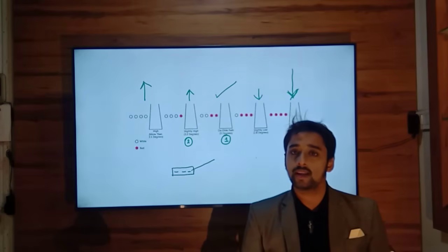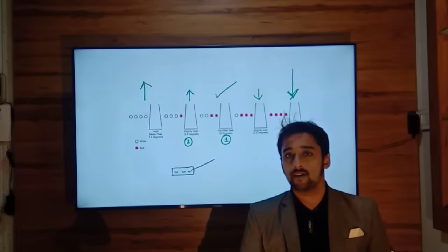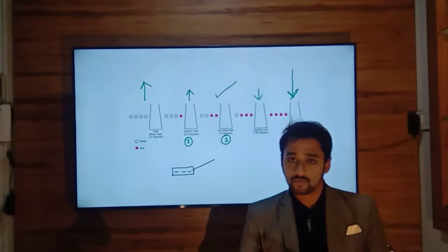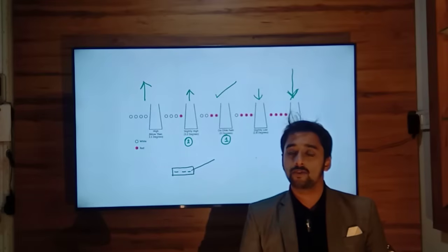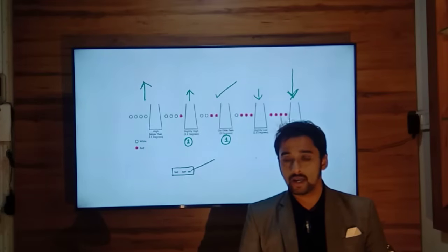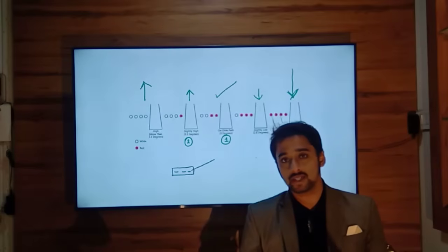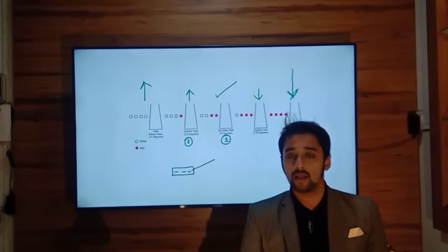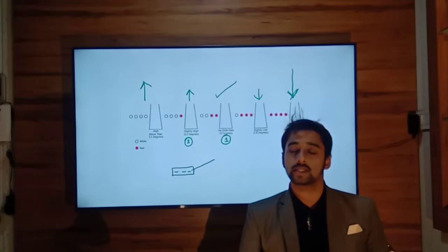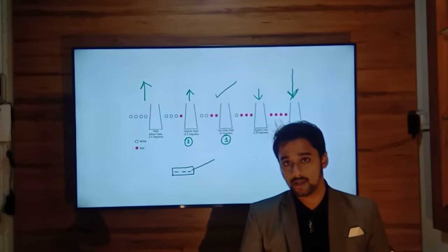You will definitely have in your cockpit, in the Cessna GPS, this OBS selector, in which if you tune your ILS frequency, it will behave like an ILS instrument and give you glide slope information and localizer information. You can use that instrument and still do an approach under VFR. That is an option available. But PAPI lights are useful for VFR pilots.